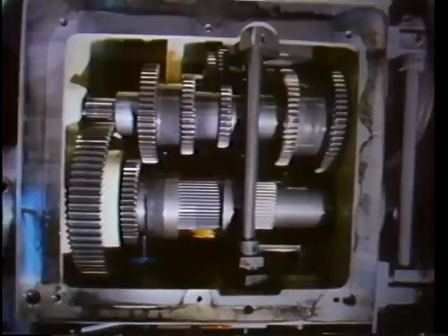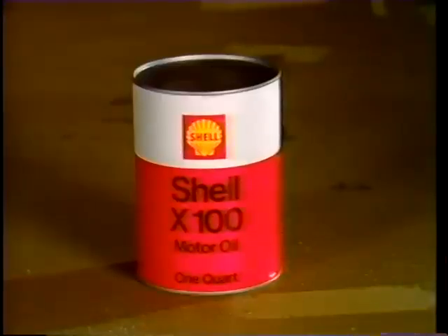Gear oil is a general purpose oil because it has many uses. Often, gear oil will be high viscosity. There are many kinds of gears, and each can be used under a variety of operating conditions. Now, those operating conditions determine the characteristics of the lubricating oil used. Gear oils almost always contain extreme pressure additives, so they can operate under high pressures that occur when gear teeth mesh. Engine oil is also used in different ways in various engines and machines.